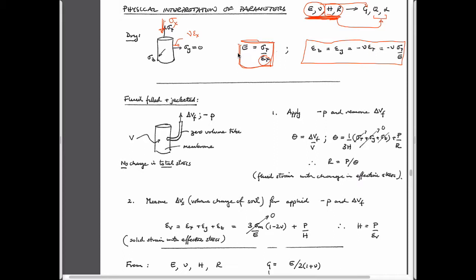Stiffness of rock or concrete is probably 40, 50 GPa. And so you always think of water as really a compressible fluid maybe, but it's not. Volume-wise, if you compress it with an all-around stress, it's close to being very incompressible. And so that's the essence of pore mechanics.